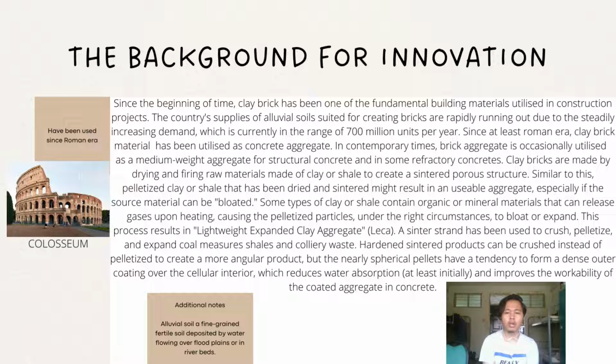Some types of clay or shale contain organic or mineral materials that can release gases upon heating, causing the pelletized particles under the right circumstances to blow or expand. This process results in lightweight expanded clay aggregate, or we call it LECA. A sintered strand has been used to crush, pelletize, and expand coal measures, shale, and colliery waste.